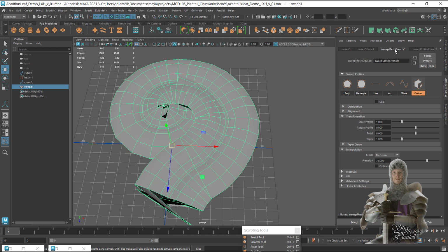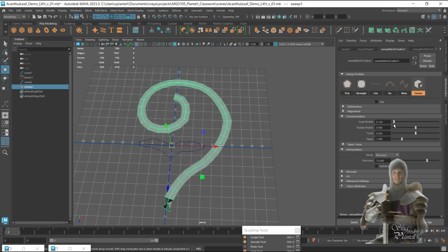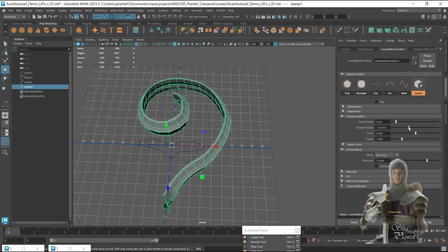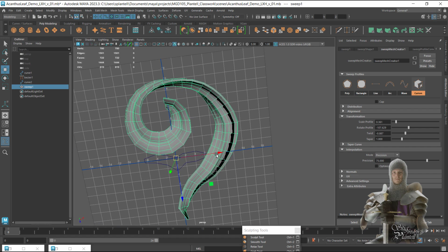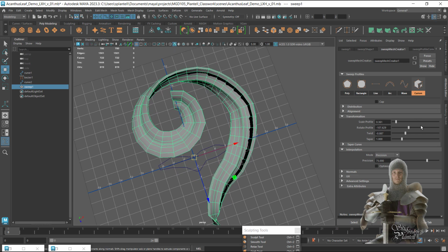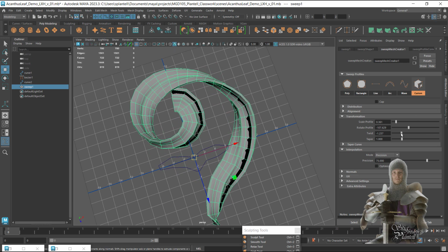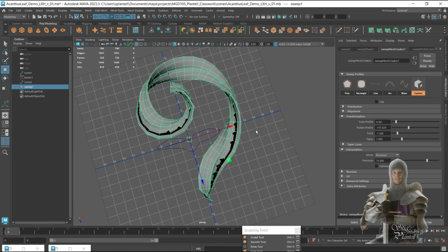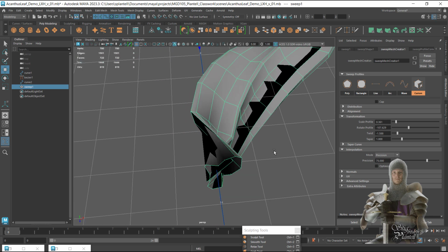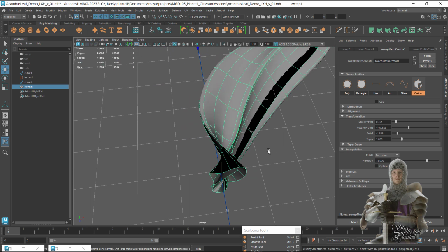You go to Sweep Mesh Creator, and you're going to make a few adjustments. You can scale the profile first of all. That's always helpful. You can also rotate the profile. Now this really impresses me here. But one notch cooler, you can twist it. So you could do a couple of things like this. And already you're starting to get something that looks very sculptural. Something that you might see on a very fancy building, or a gravestone or something, a castle. See all of these kinds of things.